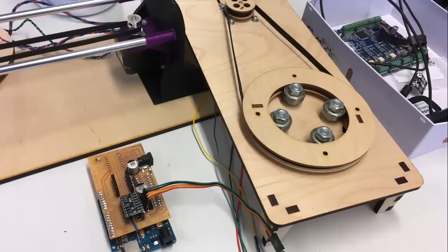The way this is built, you see there are 4 bearings which are holding this disc. This provides the stability of rotation. If you want to rotate something that is bigger, then using one central rod for turning is most likely to make this disc unstable, so it's going to wobble a lot. In order to prevent that, you can use a system like this, where 4 or more bearings are holding the disc, so the weight distribution is much more even.